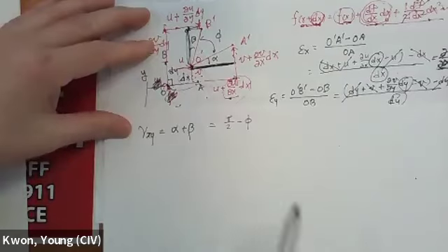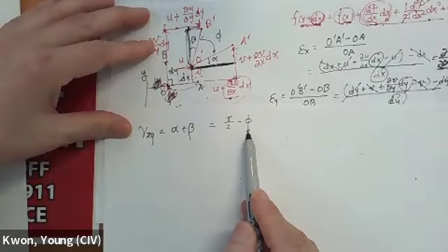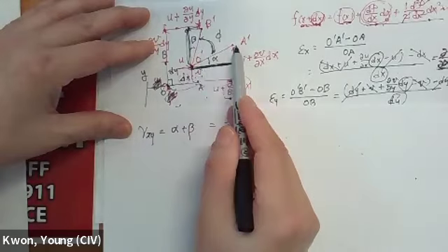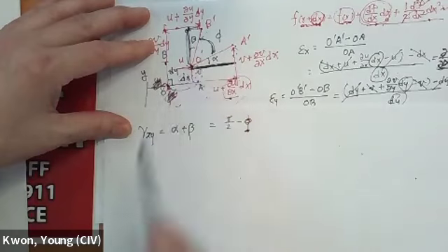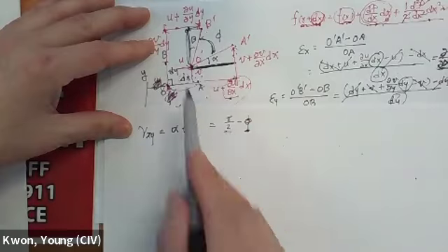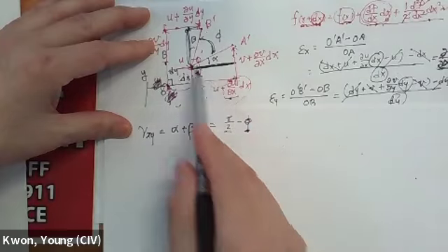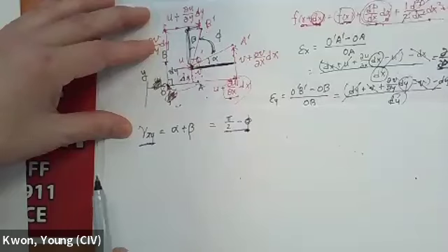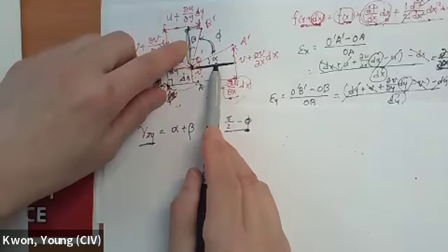Oh, what is that letter? This one, okay, phi. Phi is going to be this angle, the angle of A prime, O prime, A prime. I think she means the pi over 2 for the 90 degrees. So originally 90 degrees minus phi, that change in angle, that's the shear, which is equal to alpha plus beta.